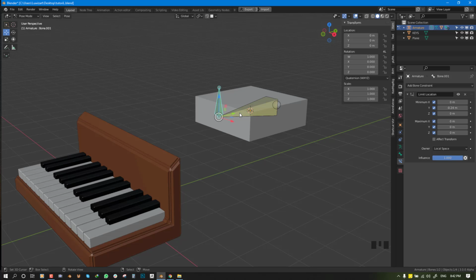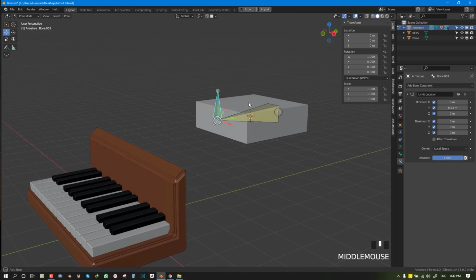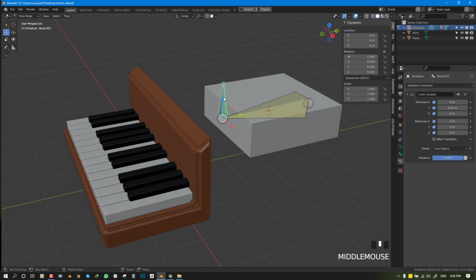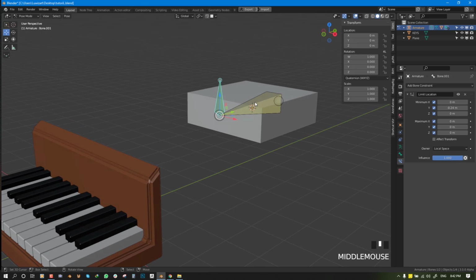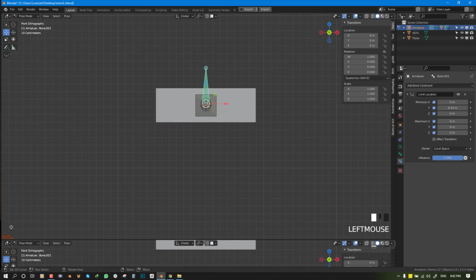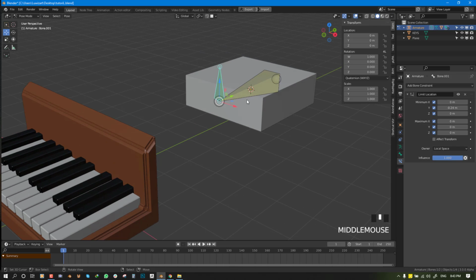The next stage is to create a dynamic constraint based on proximity, whereby if it comes close to it, then it triggers the motion of it going up and down. For that, we need the timeline keyframe. We'll just switch this. Basically switching with shortcuts, but you can come here and switch this to timeline. So you want to make sure your keyframe is in frame 1.